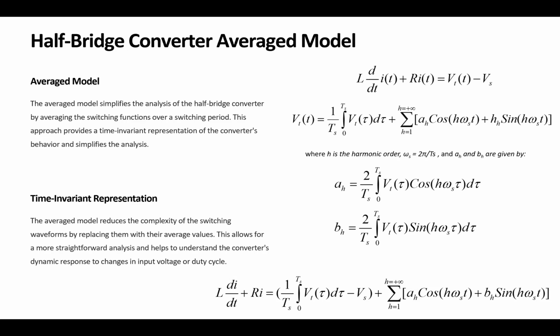Each level would face lower voltage stress, but the whole multi-level would have a higher voltage level compared to the single or regular configuration of the inverter. So that way we could provide more power, because current is constant, more voltage, more power.